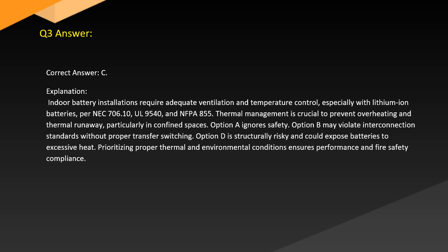Answer. Correct answer: C. Explanation. Indoor battery installations require adequate ventilation and temperature control, especially with lithium-ion batteries, per NEC 706.10 and NFPA 855. Thermal management is crucial to prevent overheating and thermal runaway, particularly in confined spaces.